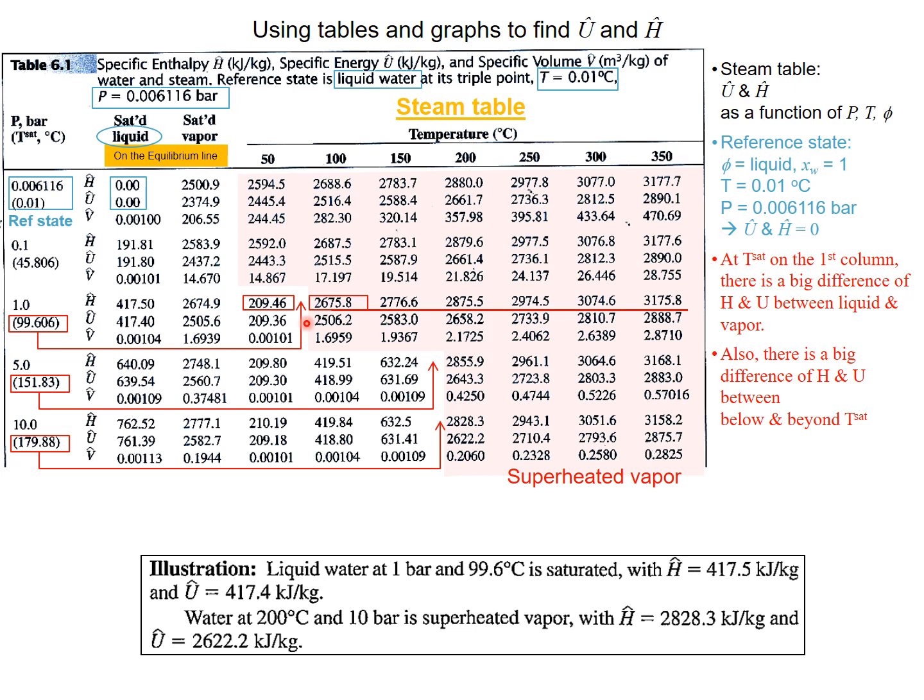Here's the saturated temperature. Before the saturated temperature, the enthalpy value and internal energy value is just 200. However, after the water molecules go to the vapor phase region, those values go to about 2500. It's a big difference at the interface of the phase change. And as temperature goes up, those energy values steadily go up to 675 and about 3000, something like that. However, the biggest jump in terms of enthalpy and internal energy was found at the boiling point, or saturated temperature.